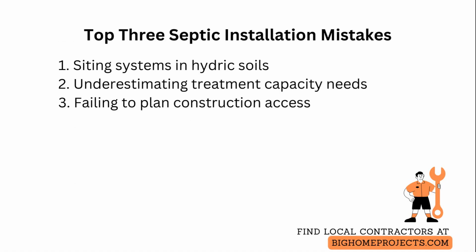Common mistakes include siting systems within hydric soils or within informal wetland buffers, which leads to nutrient loading and habitat damage. Relocate the system to well-drained upland sites or use fully contained systems that do not discharge to the ground.